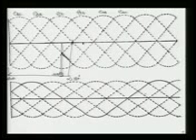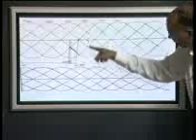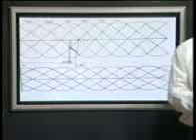Because here it is 30 degree, it is conducting, then next here 30 degree, means 60. As in the beginning I assume that valves are getting the pulses after every 60 degree. So at this point your valve 4 will get the pulse, and once valve 4 is getting the pulse, here now you can see